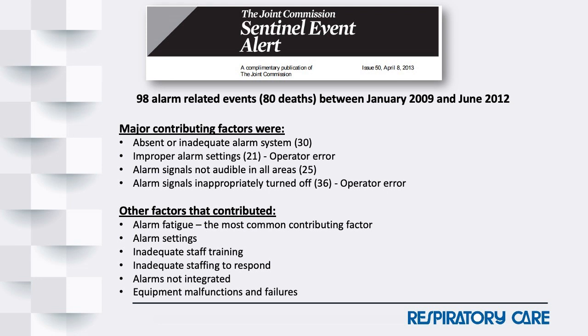I don't want to read through all the major contributing factors, but if you look at the first couple of bullet points, inadequate alarm systems were identified, setting alarms improperly, and turning off alarms, which are really user or operator error, and then audible alarms not being heard in all areas. There were other factors identified too. I would point out that alarm fatigue was the most common contributing factor, as well as issues around staff training and whether you have enough staff to respond.